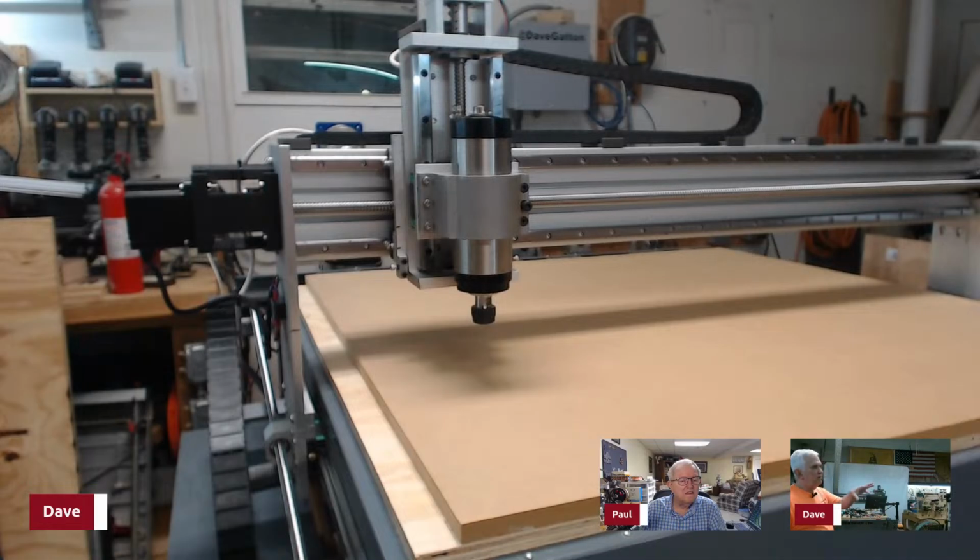Like I said, I've moved the machine around to different spots on the bed and then run that program because it does a lot of quick movements and all 3 axes moving and stuff like that. And I'm trying to get it all broke in because when you're putting something like that on a frame like I've done, just because I bolt those 2 linear rails on the side for the y-axis, there's no guarantee they're parallel. So one side was tightened up. Well, actually, both sides were tightened up.